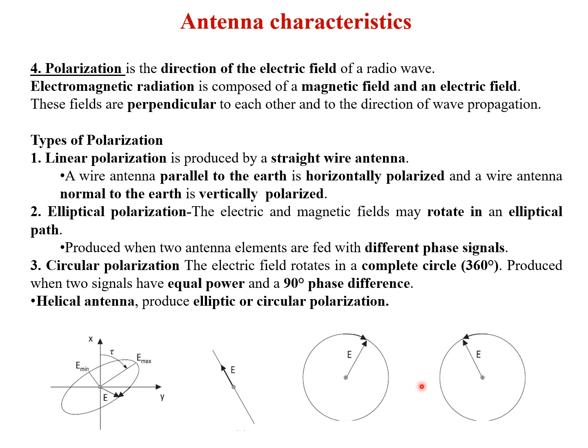The polarization of an antenna is important for several reasons. A horizontally polarized receiving antenna cannot receive vertically polarized radiation from a vertical antenna and vice versa. Similarly, right hand and left hand antenna systems are not compatible with each other. Except for directional line of sight microwave systems, the polarity of a signal may change during propagation between transmitter and receiver because of reflection. Cross polarization is the degree to which transmission from an antenna of one polarization can be received by an antenna of the opposite polarization.